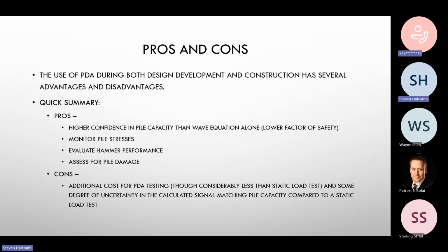But sometimes you have pre-ignition, or a really worn out hammer with more friction in it, so it's not delivering all that energy to the pile. Sometimes the diesel gets squirted in there and ignites before it actually impacts, and it slows the hammer down. You'll still get a good high stroke, but less energy hitting the pile because it's more muffled in there. So you won't really be able to tell just by listening.